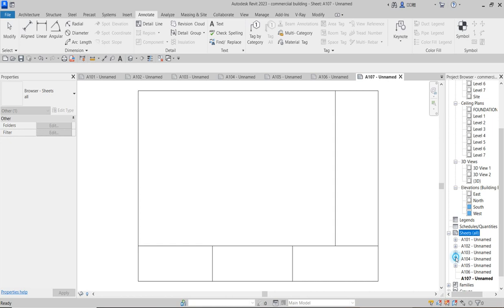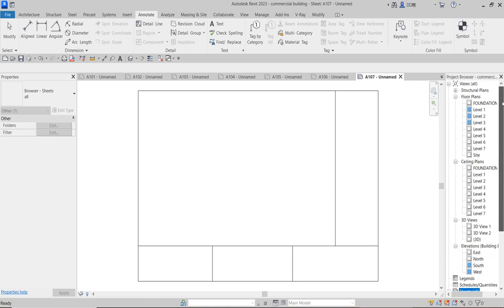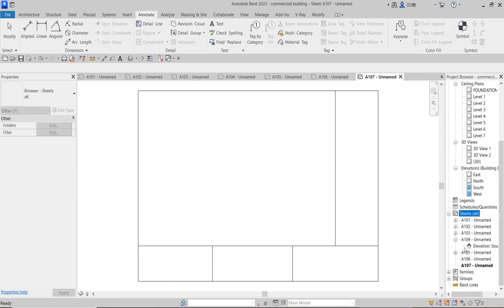So there is a general rule here, which is that you can only have one template inside one title block. You can't duplicate templates in another title block. It's not possible, but you can have as many templates inside this place. What I mean is this: if you like this particular one, south, you cannot create another south in this first paper. It's not possible.